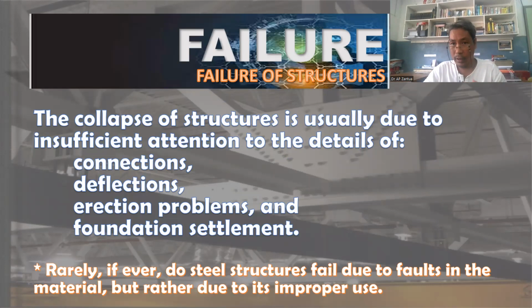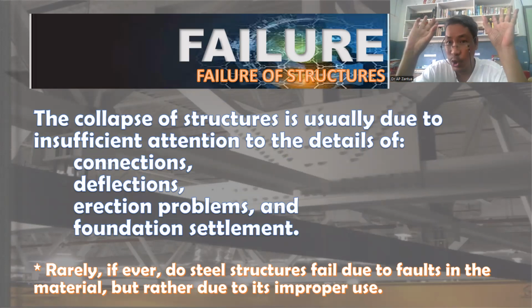Erection problem means that when we are doing the actual construction, we are putting up all the parts and doing the assembly. Because we are doing the assembly, we forget to use substantial false work. We still need the false work. Although false work is mostly a concrete problem, in steel construction we still need to use it on a limited scale, but properly.